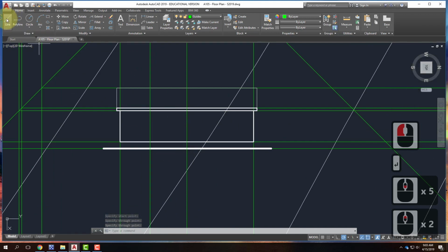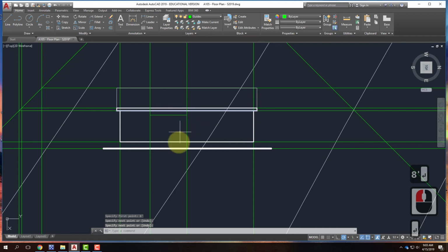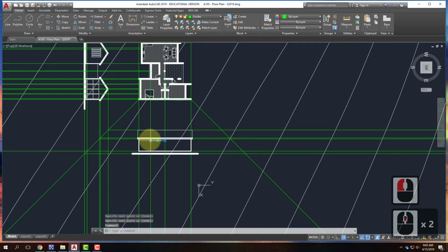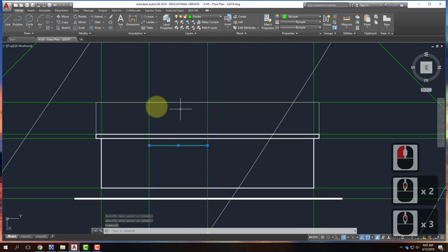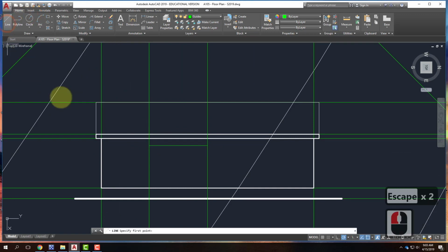I said that this was an 8-foot. So I'll go ahead and type 8 feet. And I'm leaving all of this on the guides layer because I don't want it to end up printing. I'm just using it as a reference. So there was my ceiling height for that middle section. I need to go ahead and draw my roof pitch again. So same strategy that we did before. I'll start with my line.